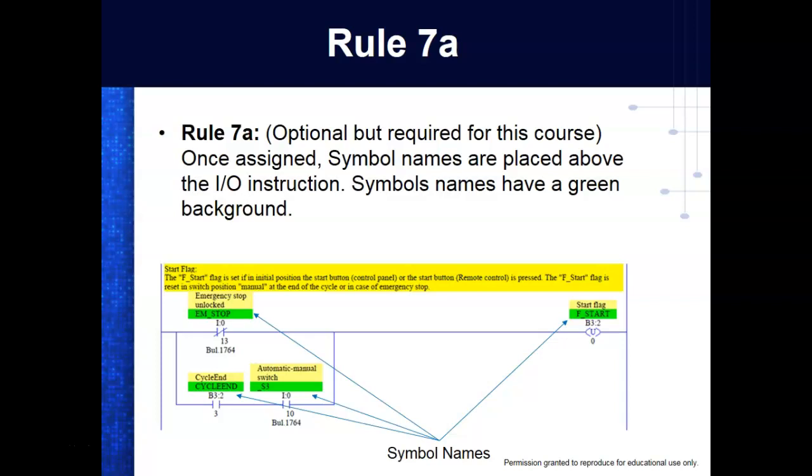And we'll show you all some PLC programs for the actual manufacturing line over there. These things are about 90 rungs long. And if you were trying to use addresses, it becomes very complicated. But if you assign an address a name, it's a lot easier to remember names than it is addresses themselves. And that's the power of using symbols. But new PLCs don't call them symbols, they call them what? Tags.